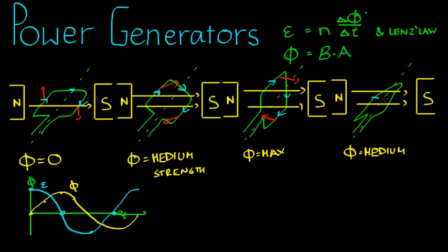Because of that, we want to push more magnetic field lines this way to oppose the reduction in flux. And you can see, if you want to do that, put your thumb in the direction of the current you're guessing, and you'll curl your fingers below under there, and you'll see that you want current to flow this way if you want to push magnetic field lines through that way. So if it's this way here, you can place your thumb anywhere on that circuit.